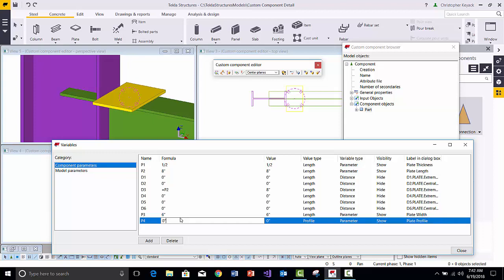Okay. And then basically the way this works is, again, we're starting all of our formulas with an equal sign. And we need to get the PL. So anytime you have a string that you're using and it's not a variable name, then we want to use quotes to enclose that. So here we want that PL prefix enclosed in quotes. If we didn't have the quotes like that and we just put PL, it would think that it's a variable name or a parameter name. So we want this to just be a string of text. Then you use the plus symbol to string these values together.